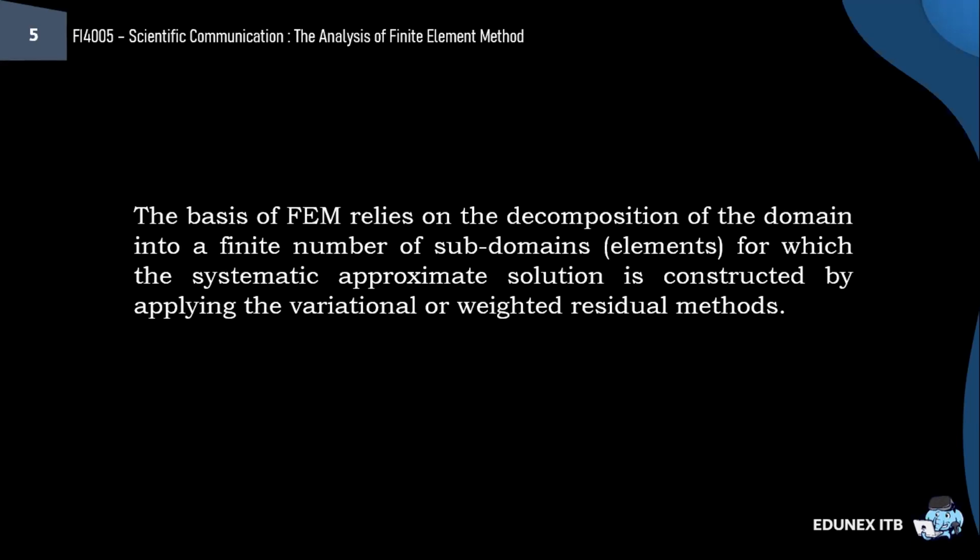These functions, also called interpolation functions, are defined in terms of the values of the field variable at specific points referred to as nodes. Nodes are usually located along the element boundaries and connect adjacent elements.